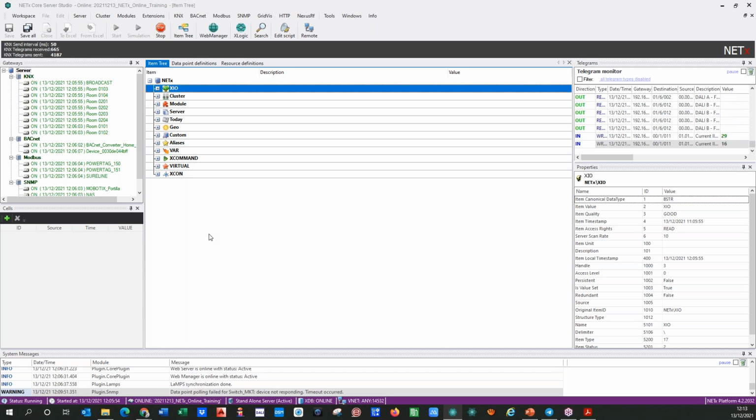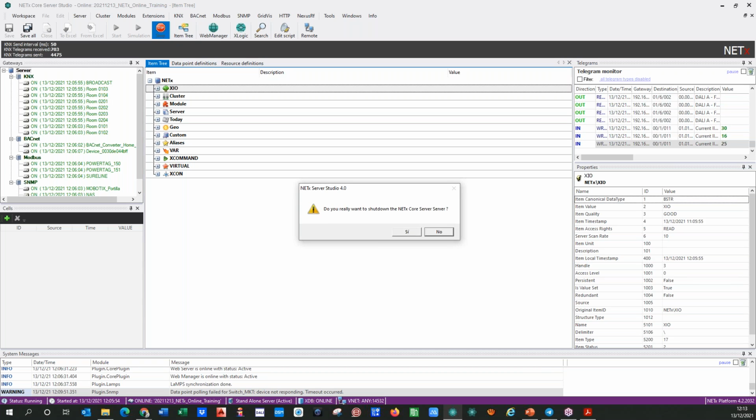So if you don't have a native driver in KNX and BACnet or whatever, OPC is a solution. But it's not the best solution, because OPC is not perfect. It has some tricky things in the configuration, and some issues with the communication sometimes. And there are two different options. I will show you OPC DA. This is the classic, we can say. Classic is an optimistic word. It's an old version, but it's the most commonly used now.